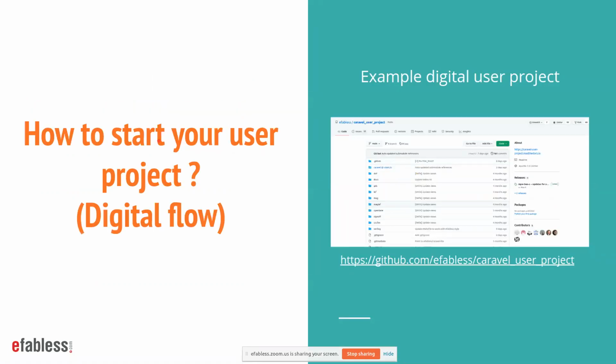So how to start your user project? This is mainly for the digital design flow. We published a template user project for digital design called the Caravel user project, and you can find it under this URL. And the repo contains the design files for an example user project, such as Verilog test benches and layout files such as GDS and DEF and LEF.